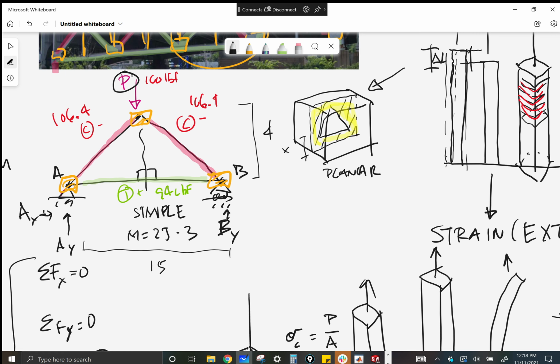Okay, from this point, we're taking this information, which is all just calculations, just geometry. We're going out from geometry into the world of materials: tension, compression, which is buckling, and shear. Actually, only compression and tension for the members. And because we know the lengths already, we're calculating failure loads with our tension and buckling equations, right? So you have to have 3 equations you're comparing for every single member.